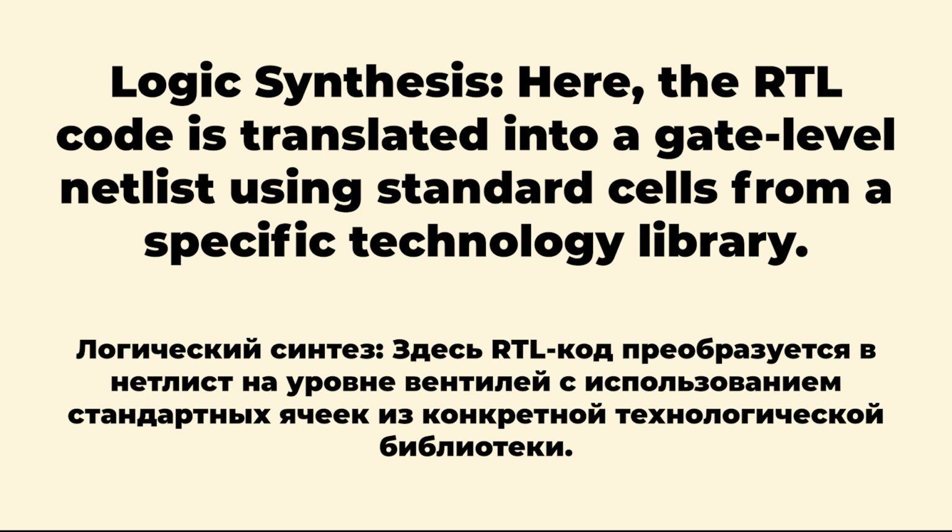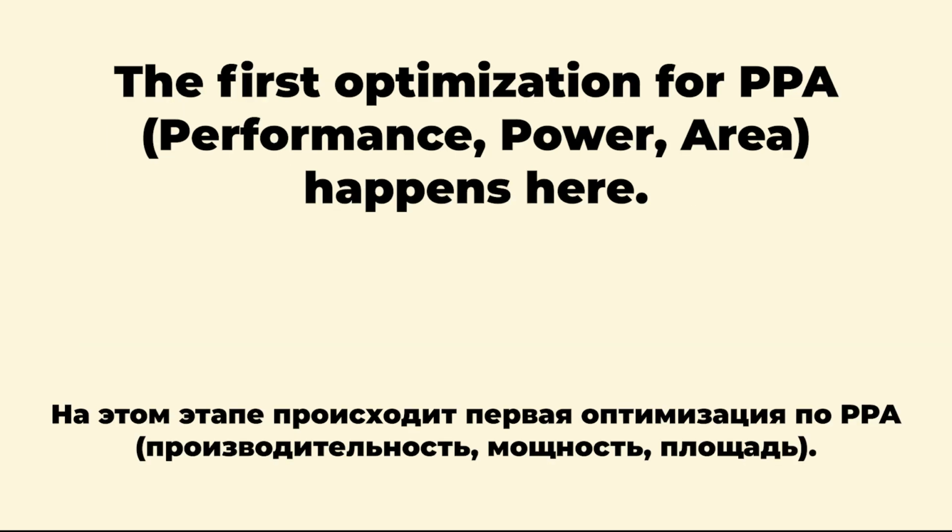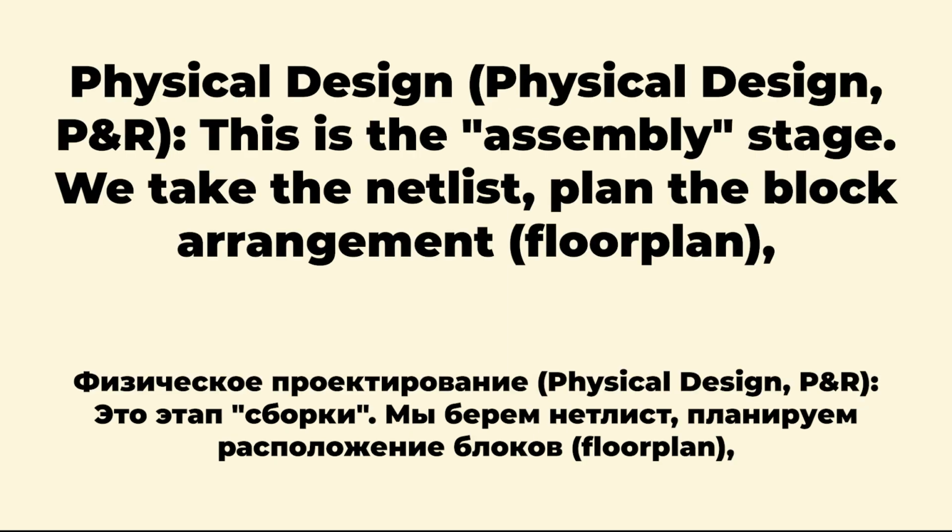Logic synthesis. Here, the RTL code is translated into a gate-level netlist using standard cells from a specific technology library. The first optimization for PPA, performance, power, area, happens here. Physical design, P and R. This is the assembly stage.